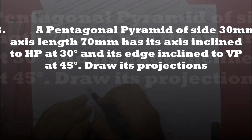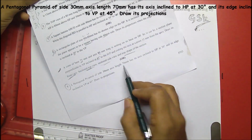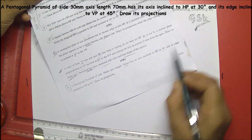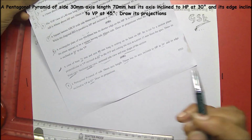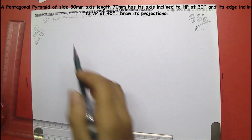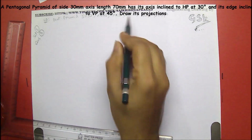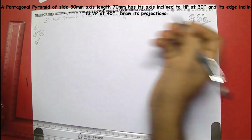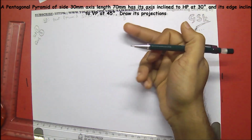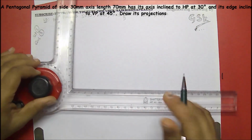8th question, this one. Here it is given that a pentagonal pyramid of side 30 and axis 70 has its axis inclined to the HP at 30 degrees and edge inclined to the VP by 45 degrees. So let's write down the given data from this question. Pentagonal pyramid, side 30, axis 70. Axis is inclined at 30 degrees to the HP, means theta is 30 degrees and phi is 45 degrees. Phi means inclination with the VP, theta means inclination with the HP, right? So let's start the problem.